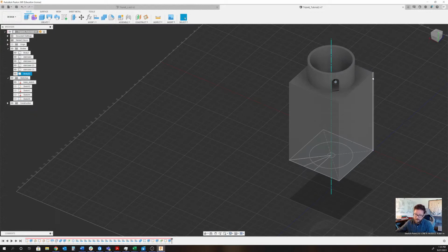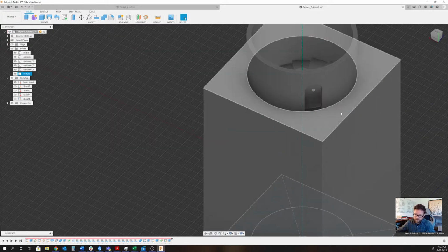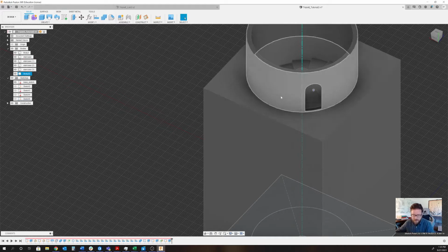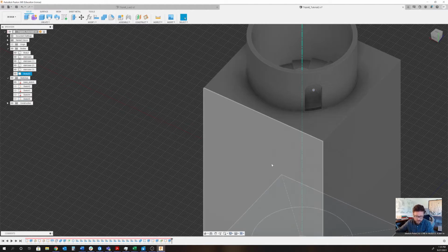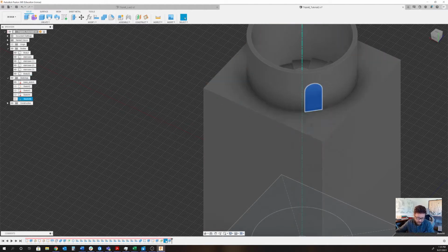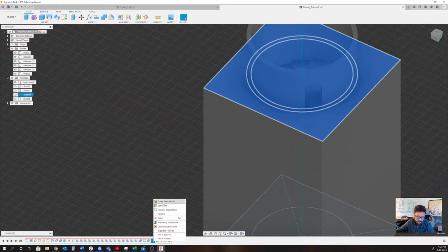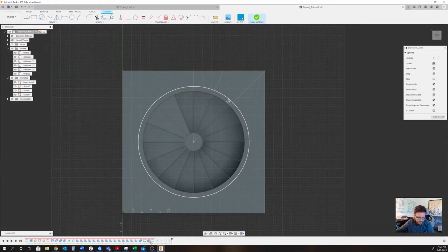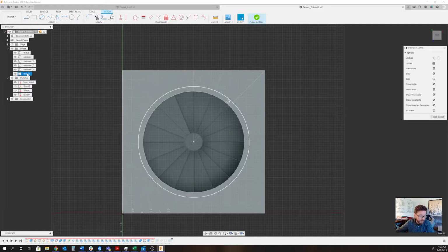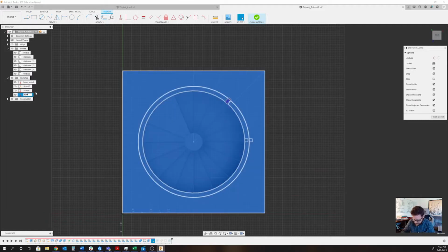Okay, good. The next thing we want to do is create our crenellated wall at the top, so our parapet, our Merlins, and we're going to make this machicolated example, so we're going to create a floating surface first. I can always go back to that same original sketch since it's on the same plane. And I'll edit that sketch quickly. We didn't name that sketch, but it's sketch 4. So I can call this top sketch, if I want to find it again here.